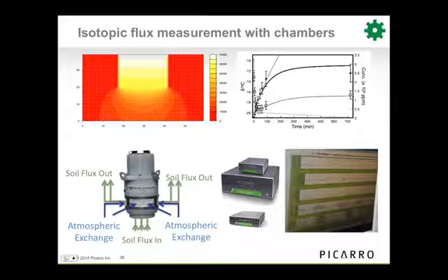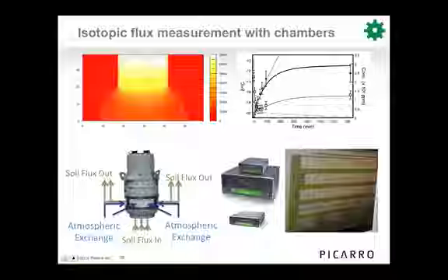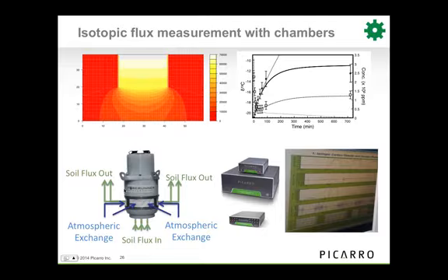So in terms of making sure that the moisture and the temperature are fine in the soil, based on our simulations, the chamber is small enough that the footprint of the chamber is not big enough that it stops thermal diffusion radially. So basically what we're doing is we're relying on that small footprint to allow the soil temperature under the chamber to be the same as the soil temperature beside the chamber, basically. And the same thing applies for the moisture content.